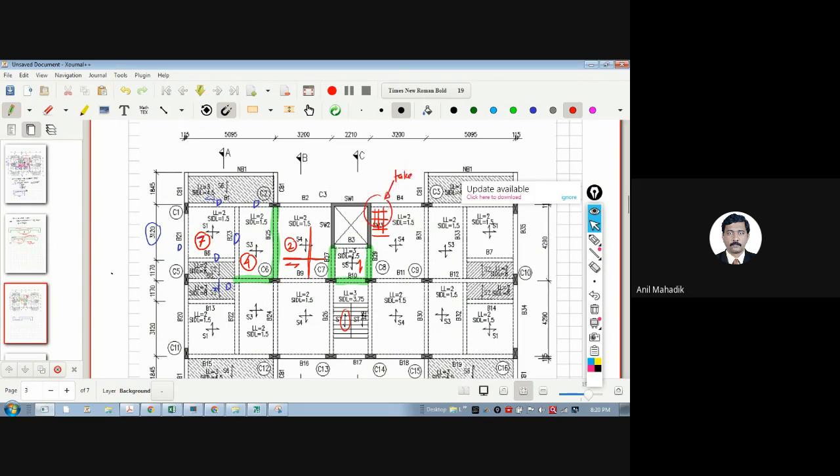So we generally avoid providing additional torsion reinforcement actually. This is taken care most of the times. And that's why I told you, whenever it is a discontinuous edge, please provide the steel even at the discontinuous edge, just to take care of the torsion.